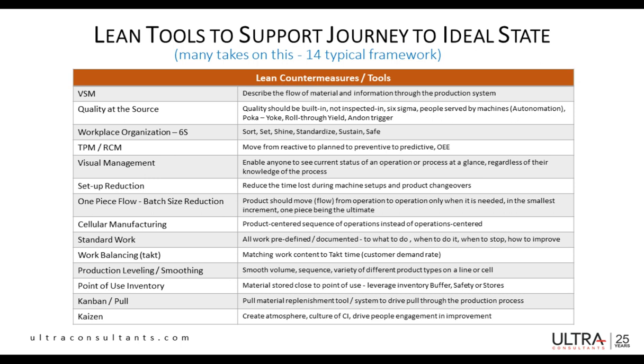I talked about one-piece flow already, constantly looking to reduce batch size where possible. And sometimes those are constrained by the physics of a process, like in the case of thermal processes. But many times that's not necessarily the case, and there are many artificial soft constraints because it's legacy thinking. Traditionally, we run 10 of these, and there's not necessarily a specific cause and effect. So striving for one-piece flow means that you have to actually unpack all of those things that drive you to batch stuff up.